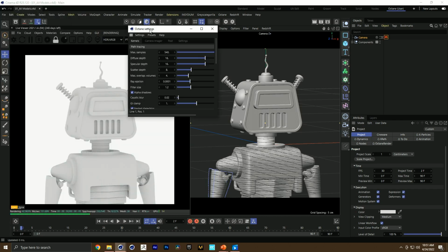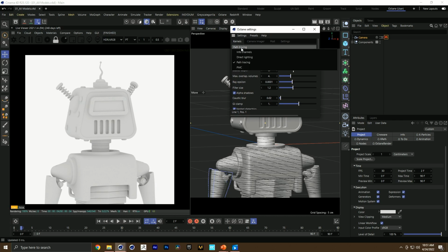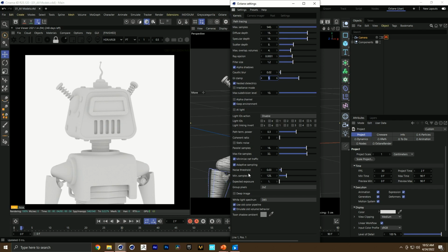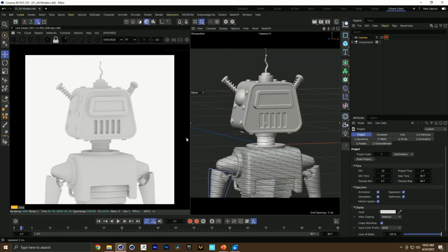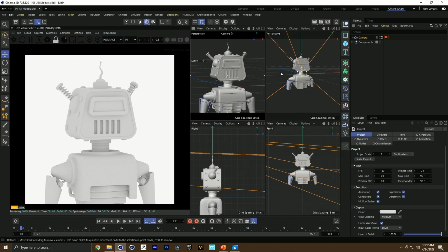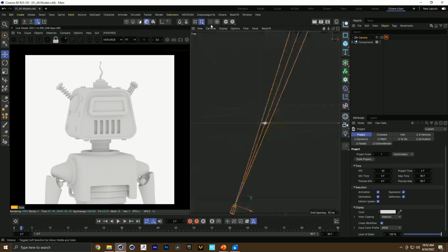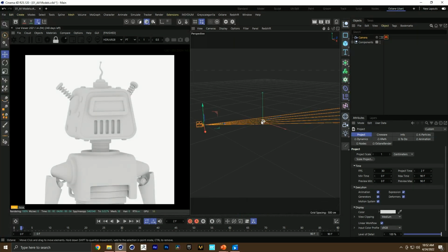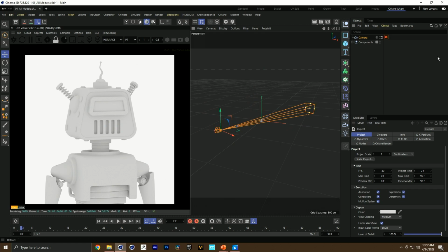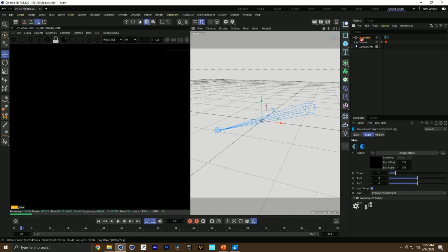First things first, these settings are not default, but normally this would be direct lighting. And this is Octane render, by the way, for anybody who doesn't know. I set the samples at 540, the GI clamp to 1, and then the adaptive sampling, I just turned it on at default. So just quick settings. To edit my lighting, I typically go out to this view, which would by default be the top view, and I just go to perspective so that I can move around and the Octane view will stay the same. So first thing I'm going to do is add an HDRI environment.